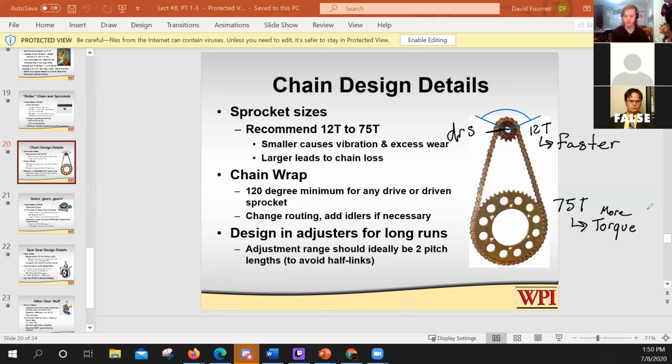All right. So if we look at it in terms of the gear ratio equation, we'll say E equals N driver over N driven. So what's the number of teeth for our driver wheel? 12. And then our driven is 75, right? So let's say that equals what? 0.16. Cool.